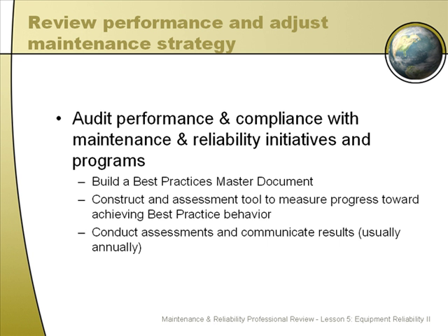Second, construct an assessment tool to measure progress toward achieving best practice behavior. Assessment tools are important because at least annually you should be doing a full site assessment to find out where you are with respect to your maintenance and reliability goals. It's going to take more than 1 year to get this done. In fact, it's going to probably take you 3 to 8 years to complete your reactive maintenance transition over to a proactive role. It'll go faster if you're organized, and that's what I'm hoping you'll get from this lesson, these lessons 1 through 9.